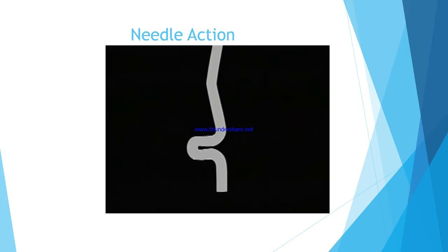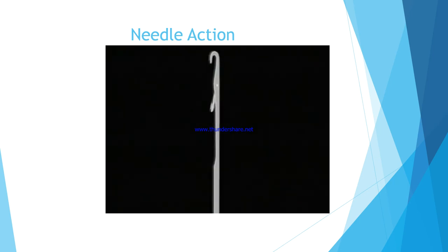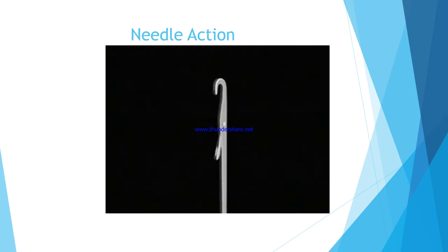At the bottom of the needle is a butt, which plays a part in controlling how needles activate, up or down. A needle with a latch is very efficient. When the latch needles are used to create weft knits, the knitting cycle can be completed without any auxiliary attachments. Here's how the latch needle works.